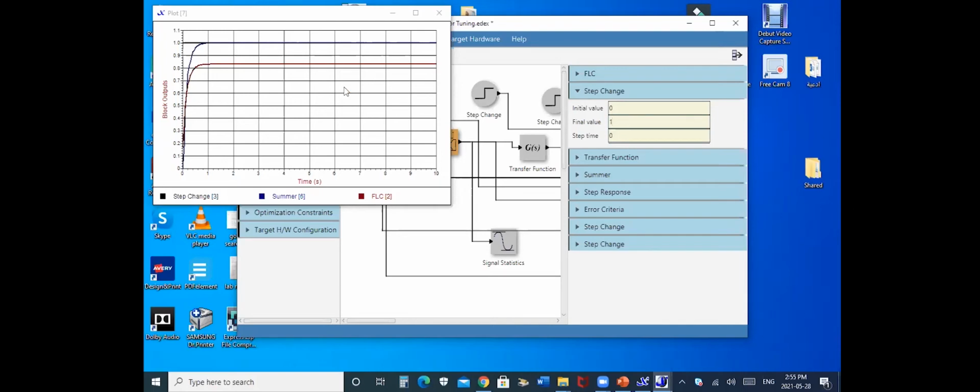However, I must say that from our experience, we found that you do not need to tune every variable in the fuzzy controller for every system. You can select which are more relevant, or you can choose some combinations, tune them, then see which combination gives you the best response. Now we can of course automate that at a later stage. Different combinations may not give you the same thing, but in the situation I've just done, different combinations gave more or less the same thing, because if your system is linear and you're adding nonlinearities to it, then you may end up with suboptimal performance because you're adding to the system more than it can take.